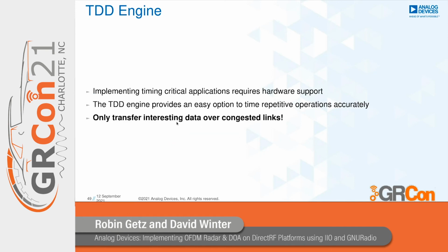Now, regarding the TDD engine, it is a really easy way, I would say, to do that synchronization and rather flexible, in case you're working with repeated operations. You could also just make the TDD engine produce 1 frame and then reconfigure it to some other values, but that's not a supported operational mode in the TDD engine GNU Radio block I created.